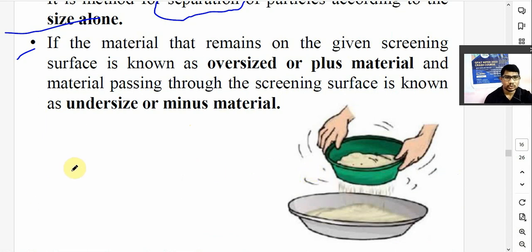You have to classify the powder, because for mixing, if the particle size is in a proper range, it will be very good mixing. If there is a very huge difference in particle size, one particle size very big and one small, mixing will not be proper. Again, you cannot ensure the content uniformity. So those factors and that importance you can read from the books. Otherwise at the end of the session I will explain from the book also.